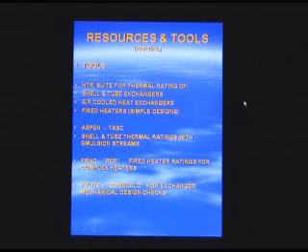We will use the PV Elite Code Calc program for mechanical checks of the exchanger design. ASME Section 8 now has a new code requirement for tube sheet design, which this program handles very nicely. That was used for some very large exchanger designs that we did for the North Slope.